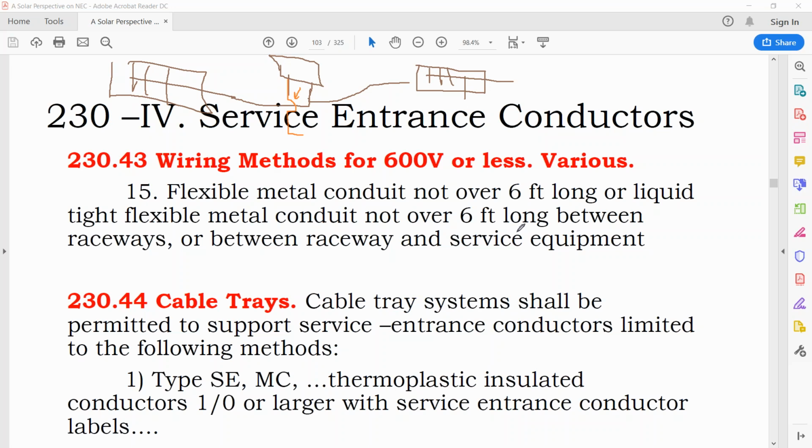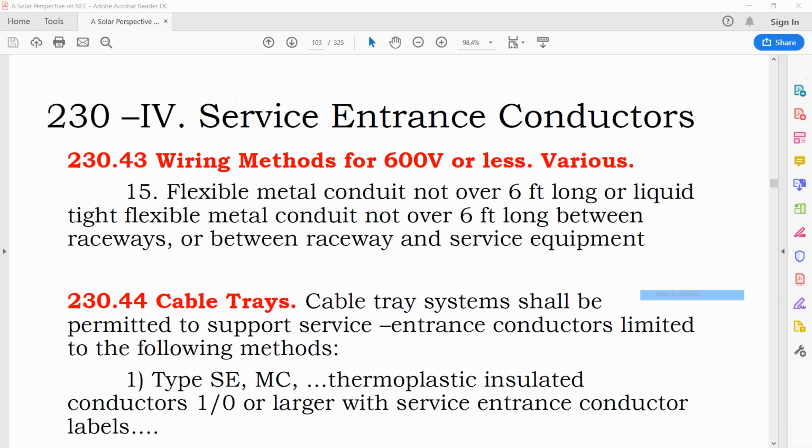Doing small bends in EMT conduit is kind of difficult. So we use flexible metal conduit for, in this case, a supply side tap. It's a service entrance conductor, so we're doing short sections for that. Cable tray rather than EMT conduit is a more professional way to go. It's also more expensive, which I imagine is why this client specified EMT instead of cable tray in their bid.